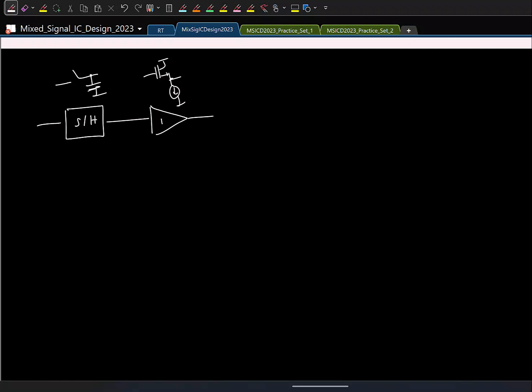So what is the maximum signal to noise ratio? 36-37 dB. And for getting a linearity of 36-37 dB, the simple source follower is good enough. You don't need to put the switch capacitor amplifier and do all that business. So now this buffered signal can go to all the strong arm latches.